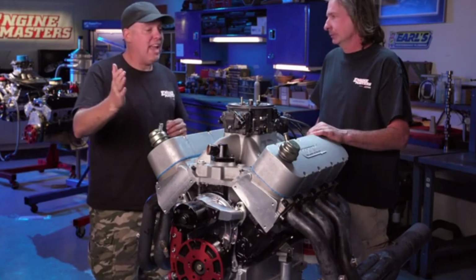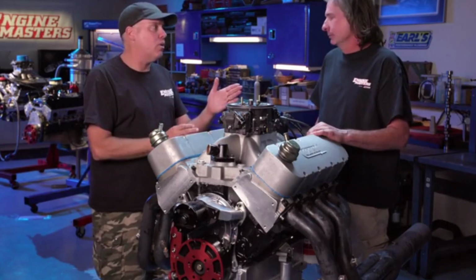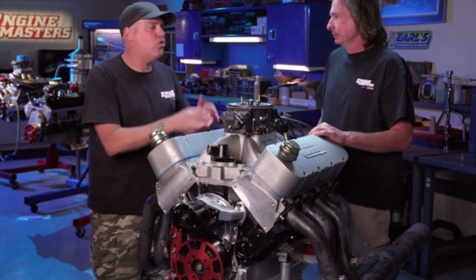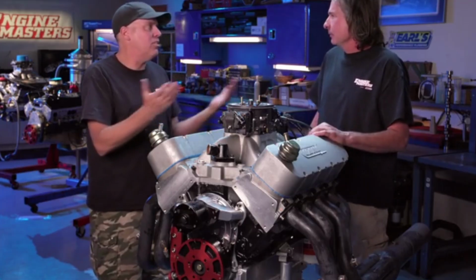So now I have to go into the caveats, which are the rod ratios that we tested in this thing were 1.8 with a long rod and 1.63 with a short rod. That is not in the range of what anybody who loves rod ratio talk considers bad. No, that's all pretty normal. In fact, most production engines fall within that range. Right, so we didn't really test screwing it up, but I think we still were able to look at a range and look at a difference. Yeah, and the takeaway for me is basically every time people think they're gonna be super geniuses and do something completely out of the norm and prove everybody wrong, they usually prove themselves wrong.